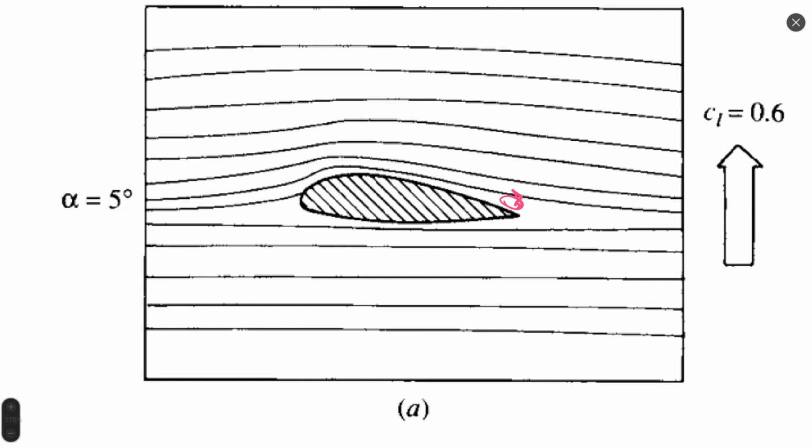Such flow separation exists as a small vortex on the end part of the airfoil. With an increase of angle of attack, we have an increase of flow separation, and then for a bigger angle, more increase, with the vortex growing. We have a growing vortex, but at the same time a growing lift coefficient. I saw such an example.